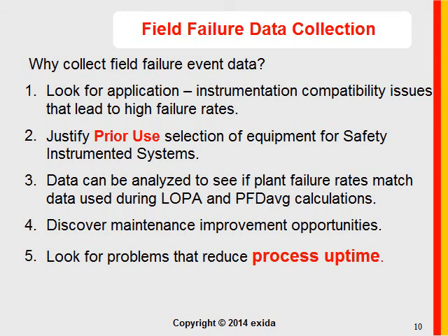All right, so when we talk about field failure data collection, why do we want to collect field failure data? Or maybe a little bit more extensive, why do we want to record anything that's happening in real life with our safety instrumented systems? Well, in short, one could argue, well, we have to. The standard requires that we periodically compare actual performance with assumed performance. Now, at the same time, the standard doesn't really provide a frequency at which we need to do that.